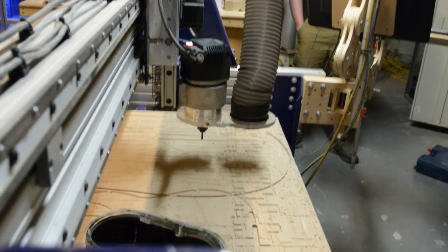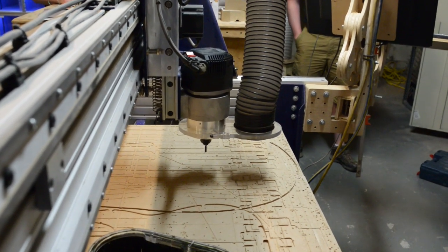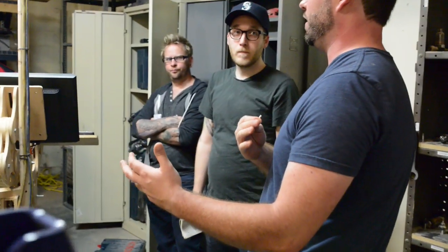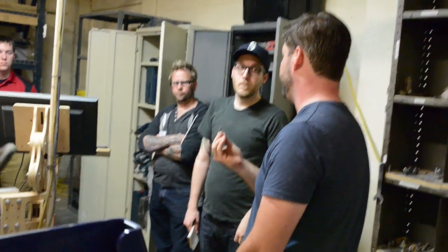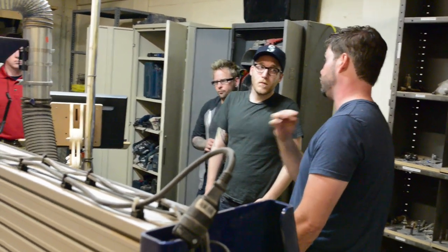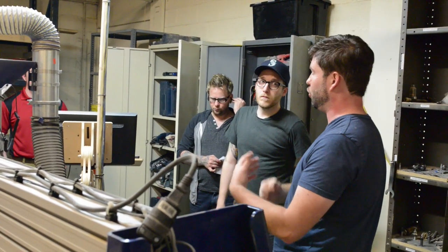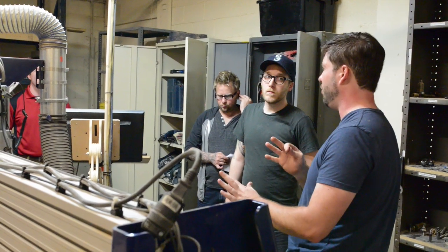So I have my straight cutter in there now. We're going to do the profile first, and then we're going to have to change it to the V-groove bit afterwards. You got to keep in mind, if we had a more complicated job than this, it might actually matter which one to do first. We might have had to have done the engraving first before we did the straight cut. So keep in mind, you might have to plan out your bit selection and your toolpath operations a little more.